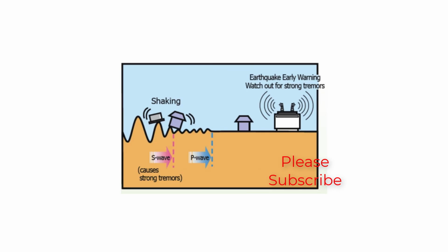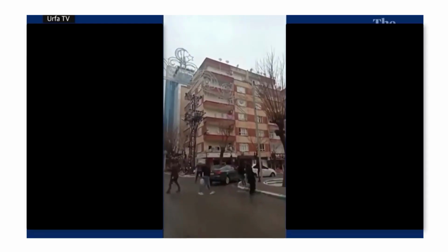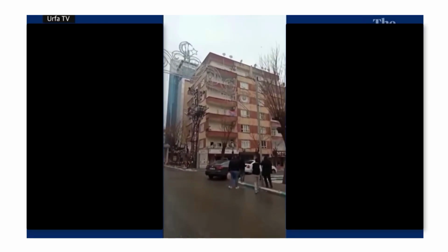Now, most of the seismic warning stations which are already there rely on the P waves, as they travel faster than the S waves, and this allows the sensor to quickly sense the powerful incoming S wave before sending the alerts to the occupants. In general, there is a gap of around 10 seconds between these two waves, depending on the distance from the epicenter of the earthquake, which is good enough for the occupants to take safe refuge.